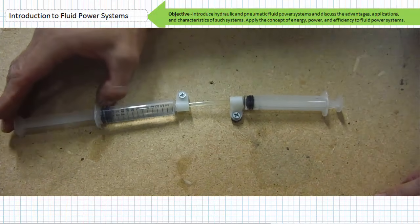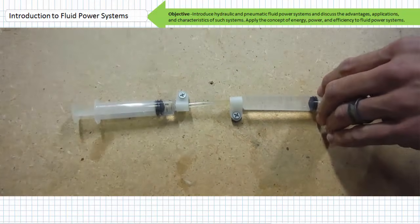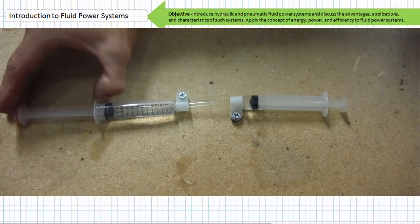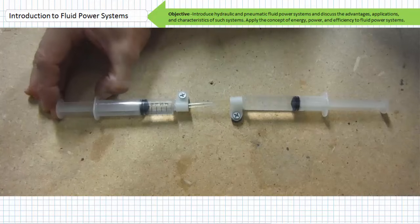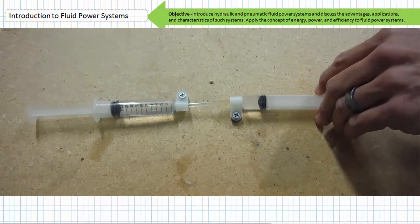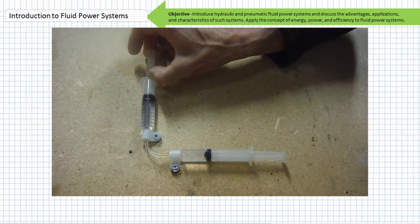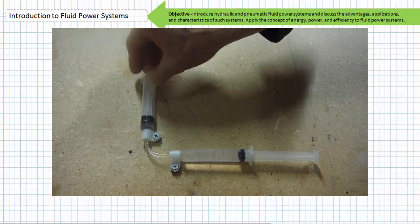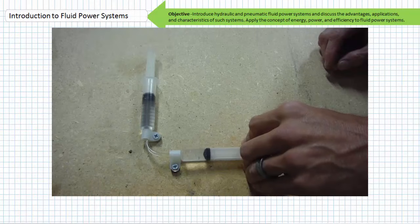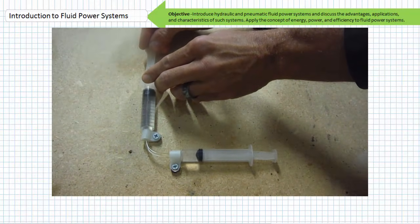As previously, I can push in one syringe, and the piston face pushes on the entrapped water, and the entrapped water pushes on the face of the other piston, and the other syringe extends. Liquid is being employed as a means of power transmission in contrast to gas, mechanical, or electrical means. As previously, the pistons needn't be in line with one another and could be angularly offset from one another. As long as the two cylinders remain linked by a passageway, liquid can be used to transfer power in this simple hydraulic system.